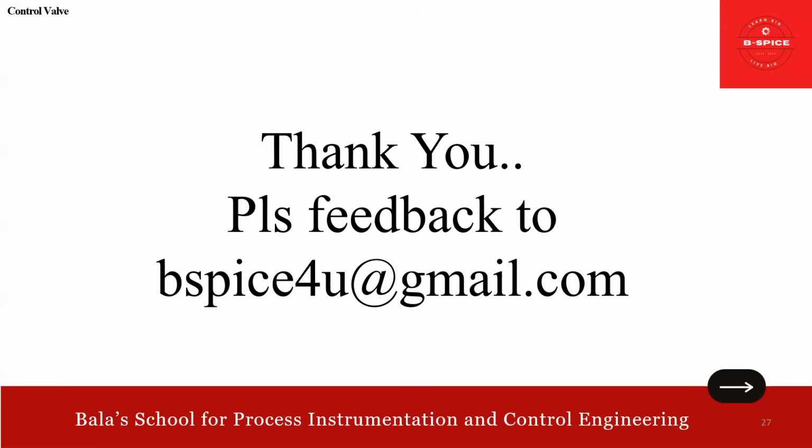I just want to recollect what we discussed. So now we know how to prepare a data sheet. A data sheet in the sense of how to fill in the general information, the pipeline details, the process conditions, the calculated results, the selected results, then the data related to body and trim, the data related to actuator, the data related to communication and software, positioner details, solenoid valve details, switch details, air set regulator details, purchase requirements, and of course, last but not least, various special requirements.